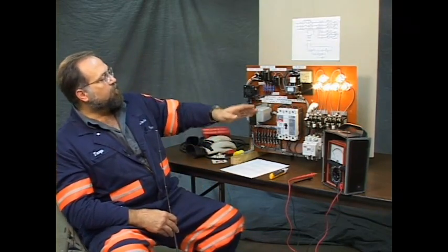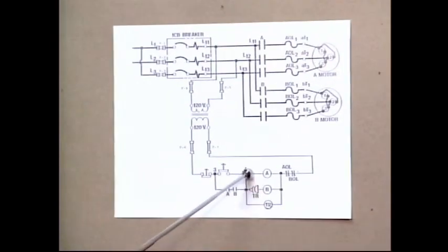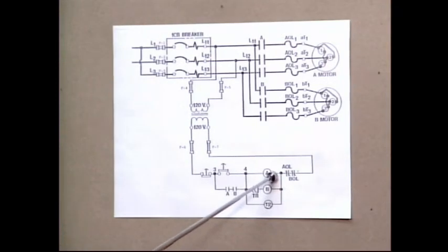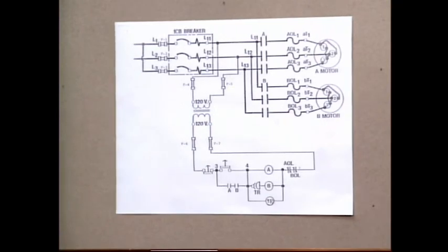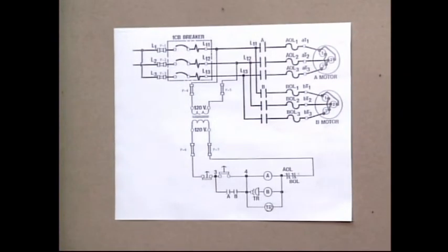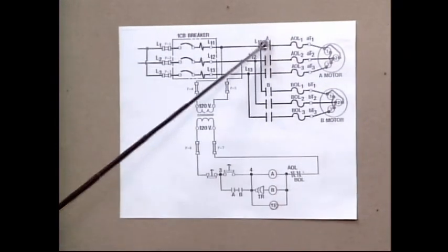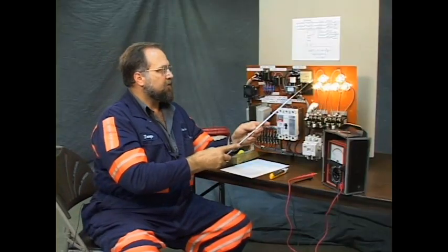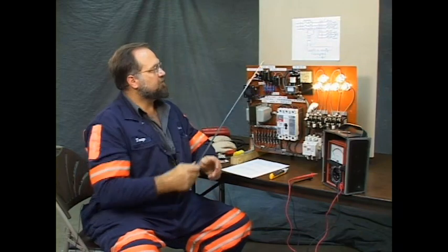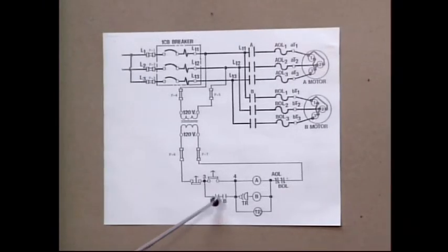Okay, normal operation. You press the start switch, that's here. Current flows immediately without interruption to A coil through the overloads and returns to the control transformer. You have a circuit. It's made a path all the way around. A pulls in. When A coil is energized, these contacts close. The motor is energized. The motor is illustrated by these three lights, as shown on the drawing. Now, when A starts, you're still having to hold the start switch. You don't have a holding circuit until B starts.